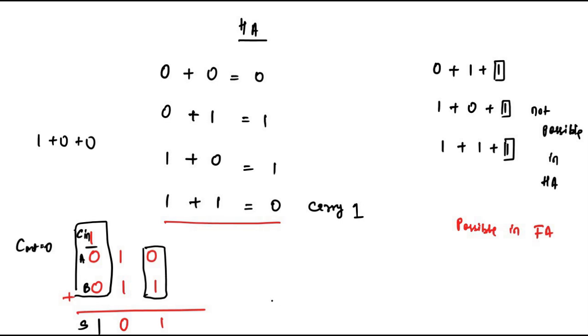For example, let us say we had an operation like this, where there is a carry of 1, we have the 2 input bits 0 and 1. So here 0 plus 1 is 1 and 1 plus 1 is 0 with a carry of 1. So here the result, the sum output will be equal to 0 and the carry at the output side will be 1. 3 bits.